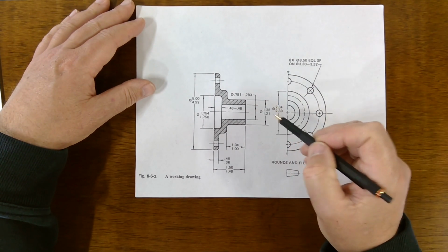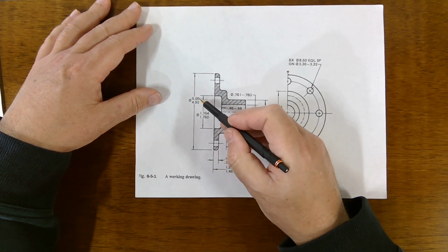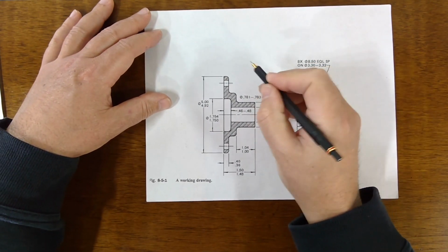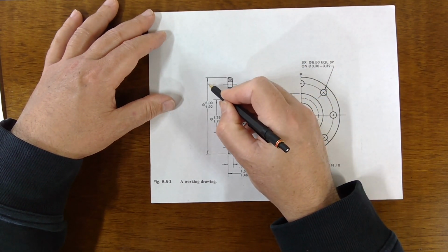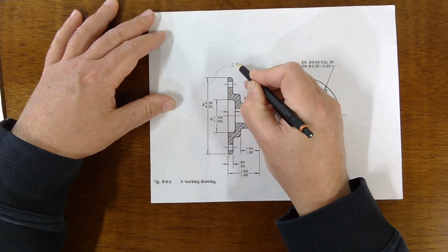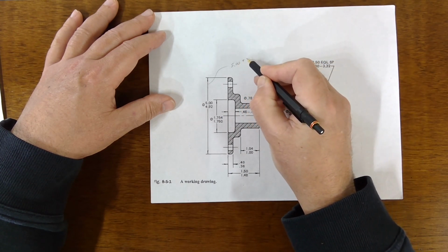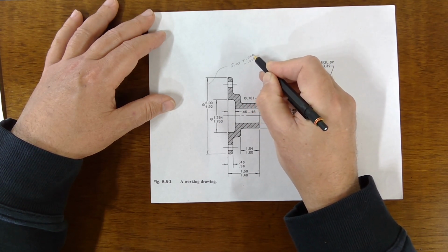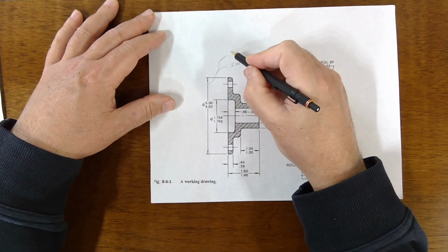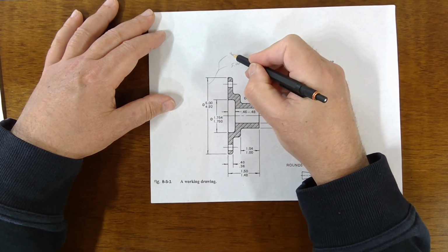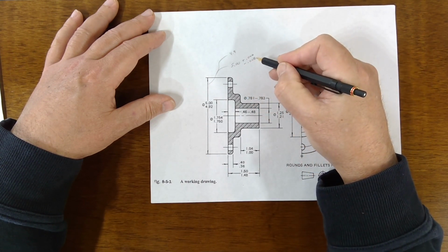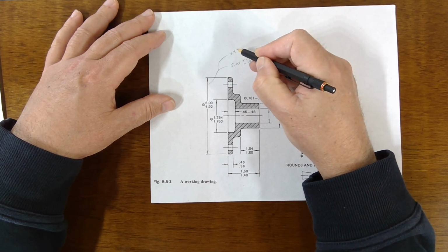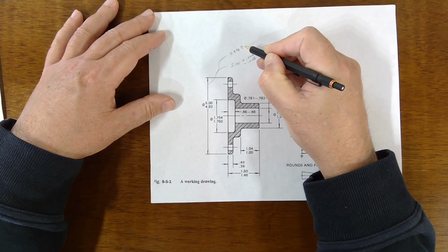So those are 2 of the ways that you represent tolerances, either as numbers on top of each other, or this thing. The other way you might see this is that this dimension could be specified as 5.00 plus 0.000, minus 0.008, something like that. Or it could also be specified as somewhere in between, like 4.96, since the range is 0.08, you could go 0.04 over on either side. So the middle value between these would be 4.96 plus or minus 0.04.